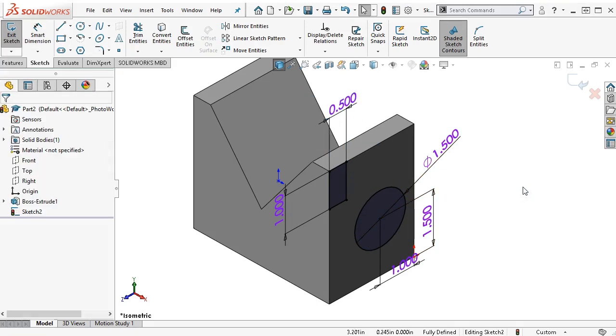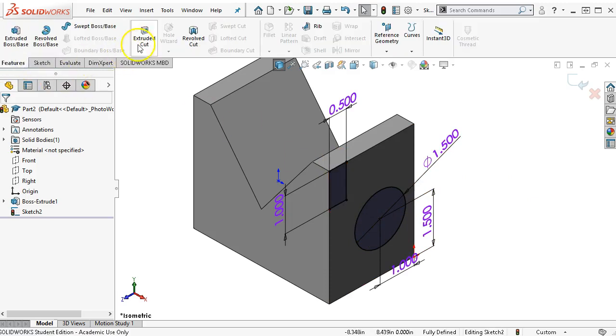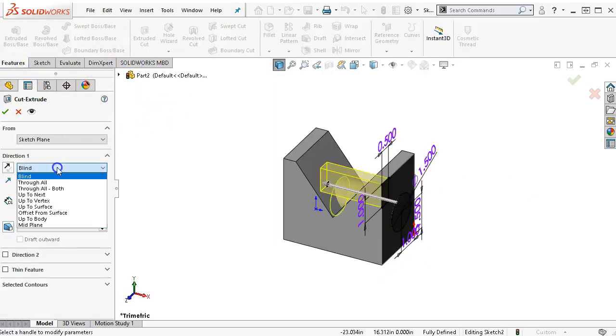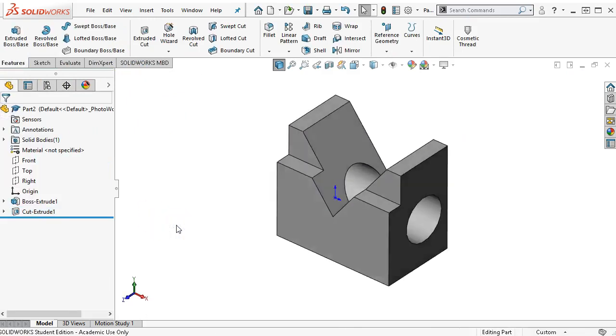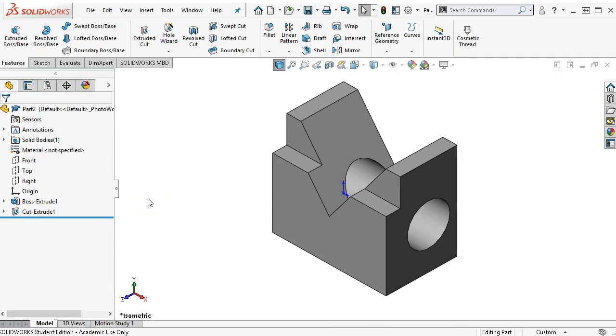If there was something that was an advantage or potentially an advantage, this could be a feature and then a second feature. Alright, so cut extrude, we'll give it the through all, and apart. So a lot of times you won't see any great advantage between contours and regions and just the profile nested sketches. So you pretty much take a pick and develop strategies as you go.